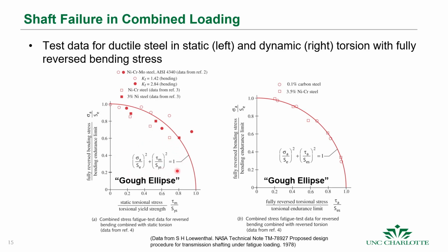and we get this equation here of the Gerber ellipse. Now notice it looks similar to those equations that we used for the modified Goodman diagram. Historically these equations were used, and we introduced expressions that included the diameter so that we could include the loads, the yield stresses, and the endurance limit, and back calculate the diameter. And we'll show you how to do that. We don't use this method anymore, but it is useful from a historical perspective to understand where it comes from.